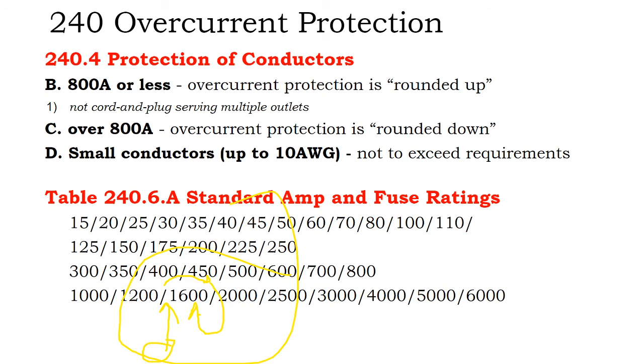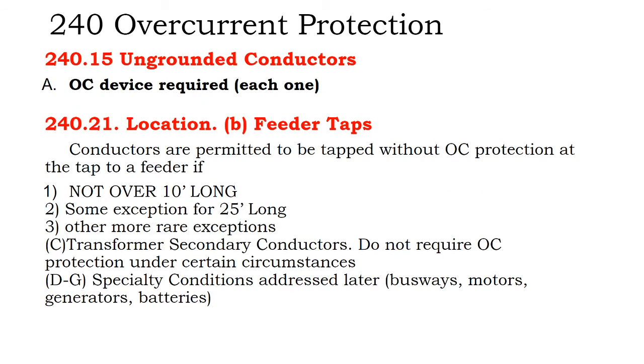They won't be burnt up, because that breaker will open before the conductors burn, provided that it's an ideal ground fault where the current is just going through the circuits and then out to ground through the fault without anything funny going on. Anything funny being like the cables are stripped and touching the roof deck, and the heat from the cables is burning up the roof deck, and that causes other kinds of issues.